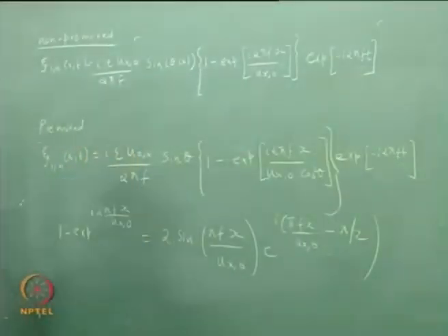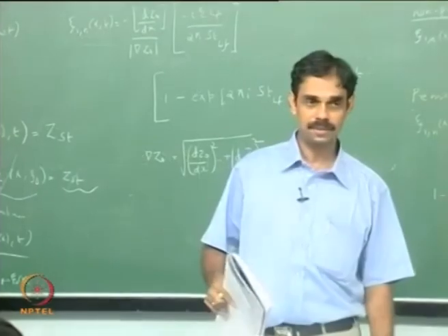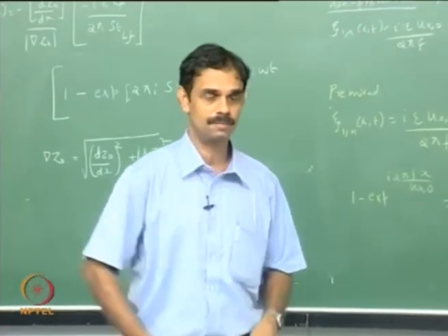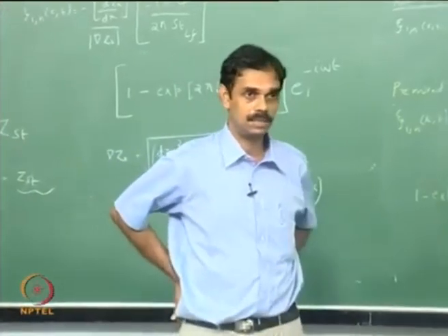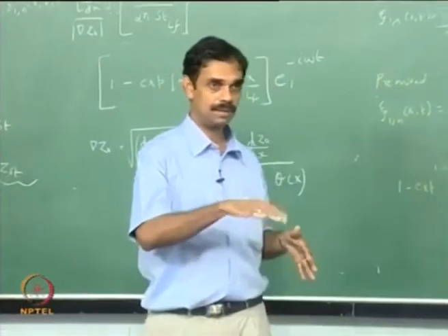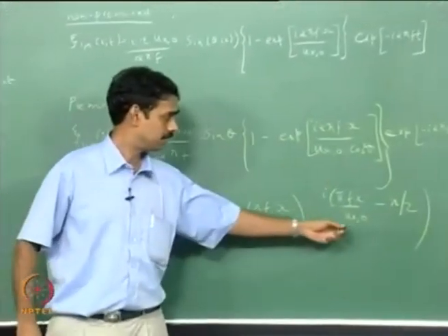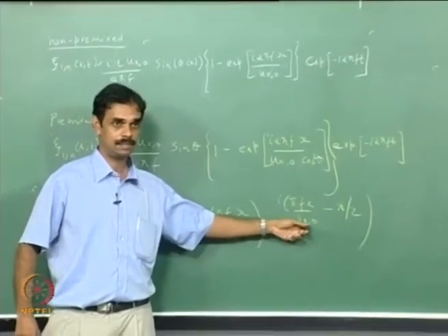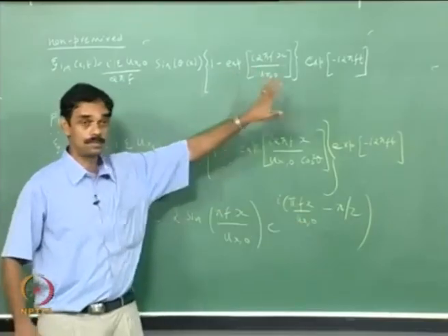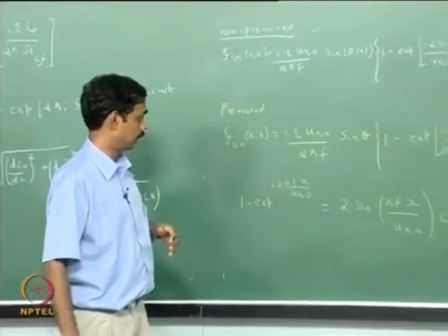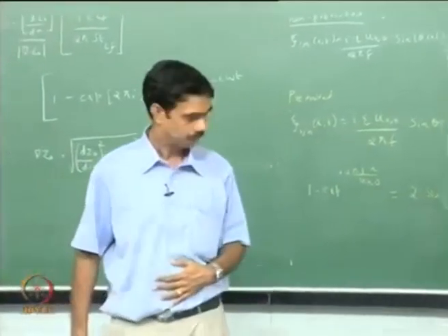So we have studied two different physical phenomena, one with premixed flame and one with diffusion flame, and we are able to see the commonalities, that is both can have wrinkles and both can move. But here the wrinkles move with the convection speed, whereas in premixed flame there is of course a balance between the flame propagation and the flow. I think that is it.